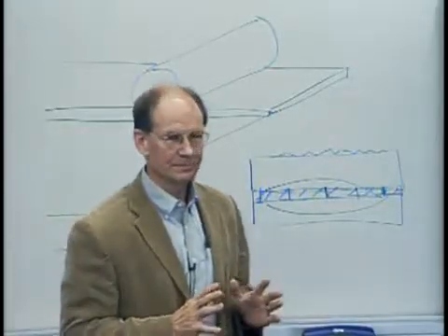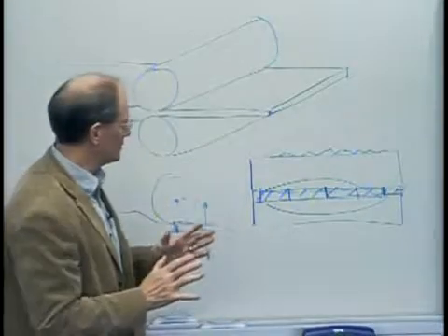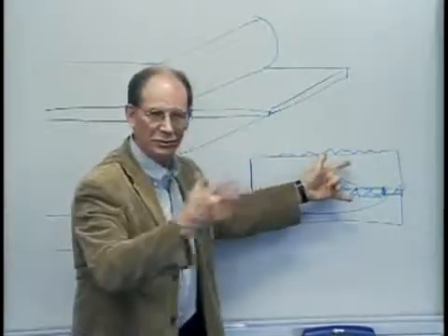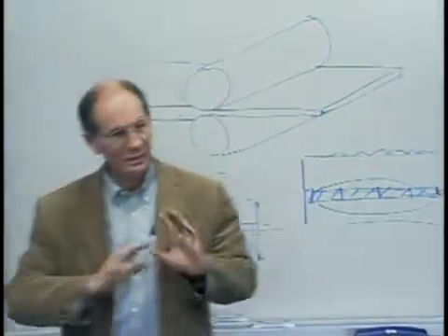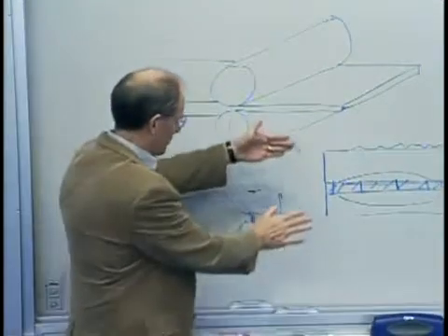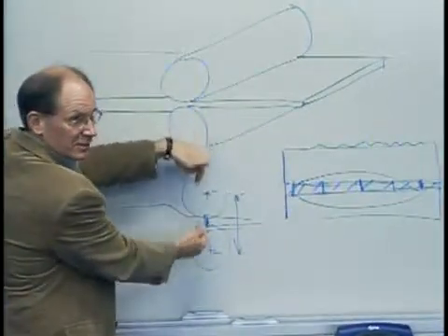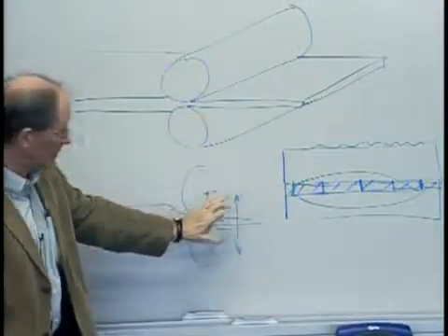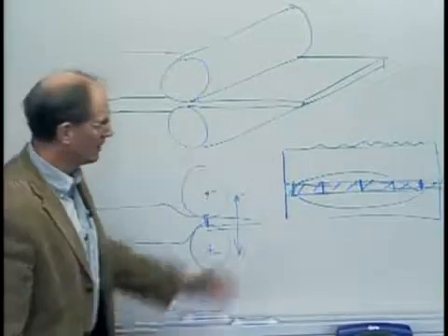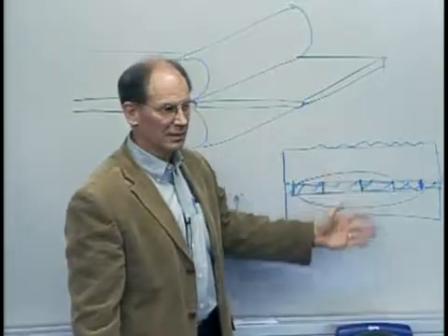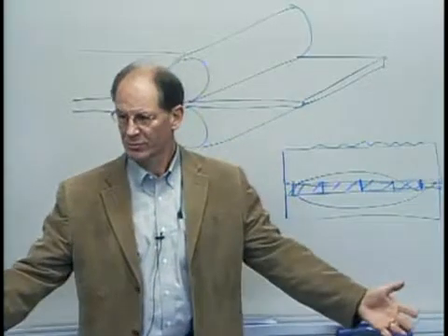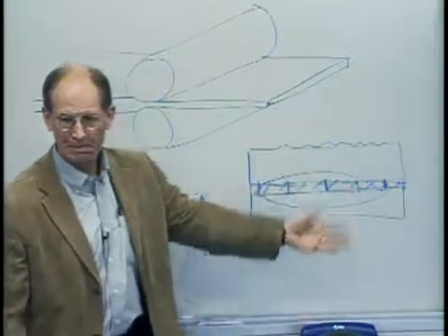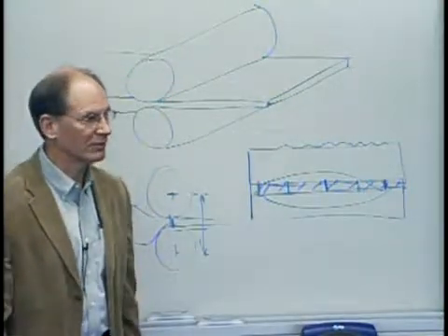But yeah. So in this particular case, notice these two different modes of interaction lead to two different ways of controlling it. In one case, it's very simple. I'm going to buy a servo system. It's going to be really good. It's going to be very stiff. And I'm going to say, make that 0.02 of an inch gap, and you get 0.02 of an inch gap. In the other case, it's like, oh my gosh, I've got to change this spatial distribution somehow. The extreme case is to shut the thing down, put in a new set of rolls, and the other is to come up with some clever way of deforming it.